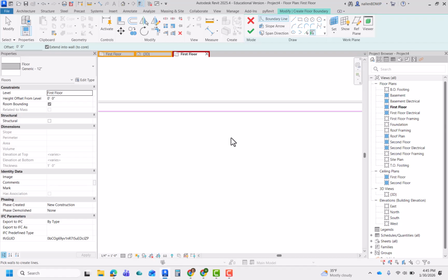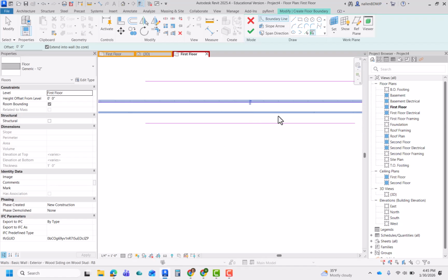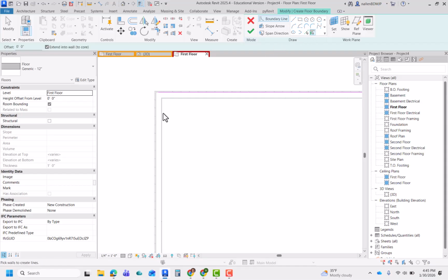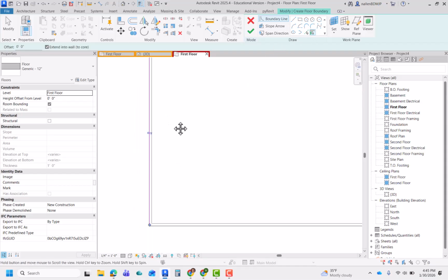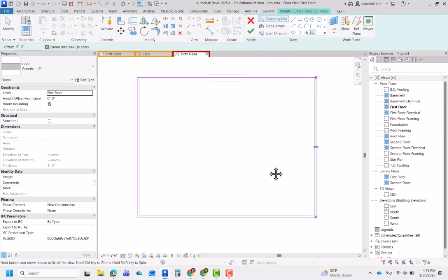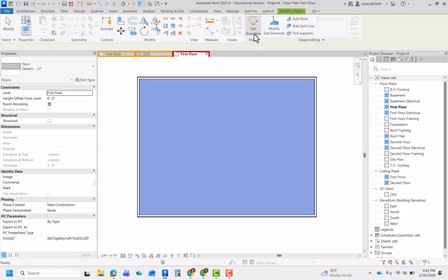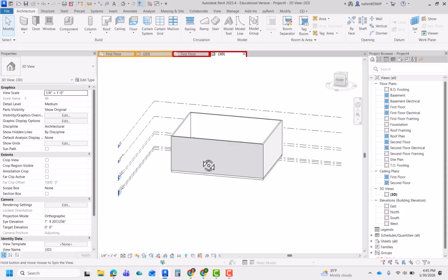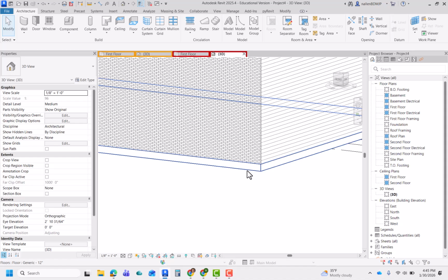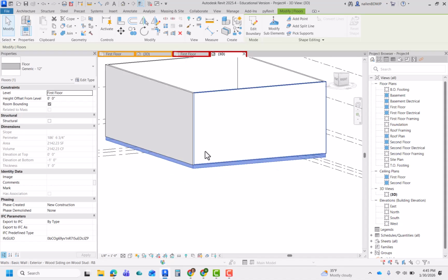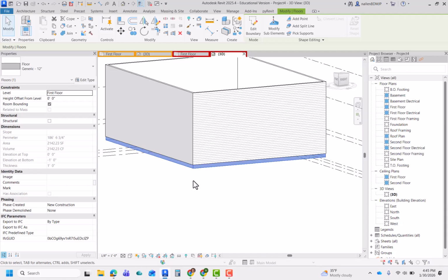And we want the wall to have something to sit on, so I'm just going to switch this around. I'm going to flip it, and now you can see the pink line goes to the outside edge. And we'll continue that. Hopefully we'll keep putting it on the outside edge. There's all of them, and I should just be able to accept this. And it didn't ask me the question that I was waiting for, which is, do you want this floor to join geometry with those walls? The answer to that would have been yes.